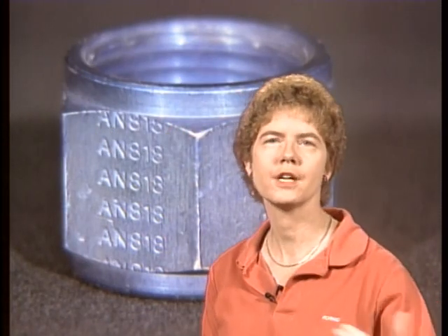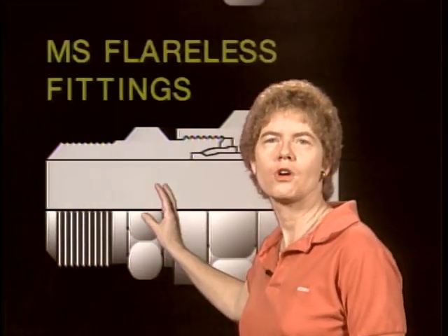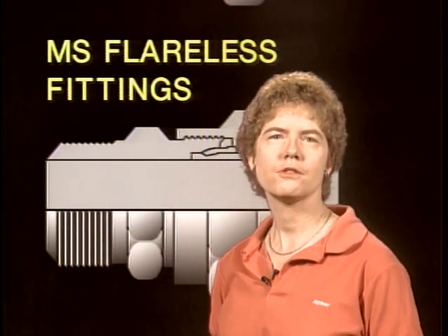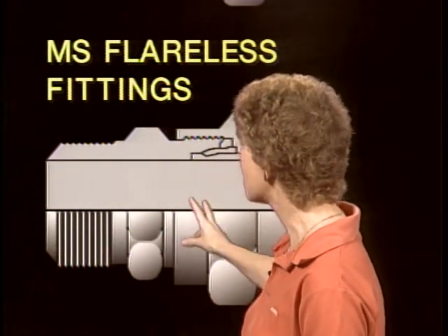Now, there are also fittings that you're going to be working with that are military standard or MS flareless fittings. And the MS flareless fittings are not tightened with torque. They are tightened by turning the nut a specified amount after the sleeve and fitting sealing surface have made contact. Instead of being torqued, they are tightened a certain number of rotations, a certain amount of turns or partial turns after the sleeve and the sealing surface have made contact.